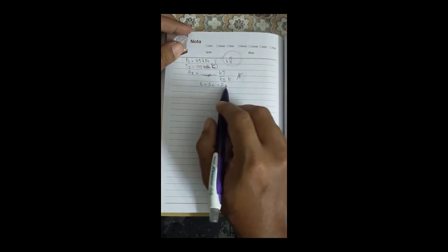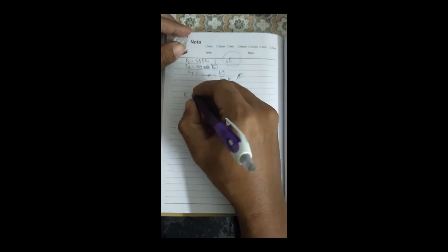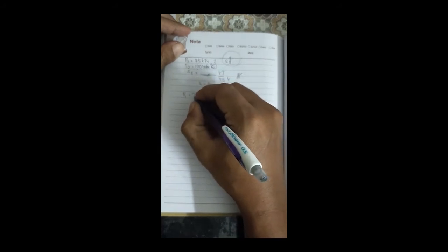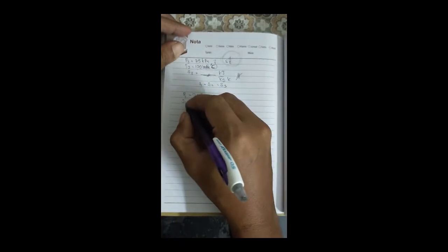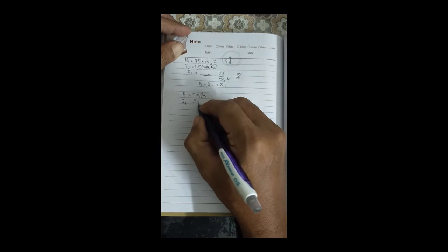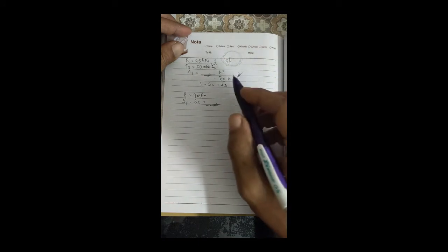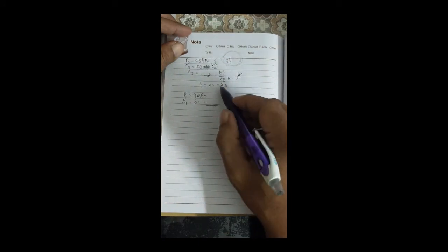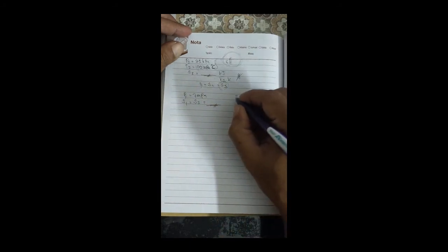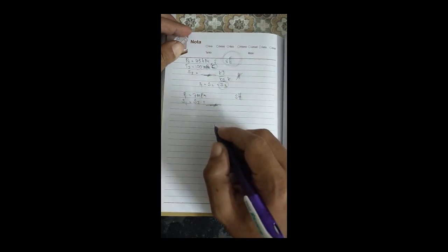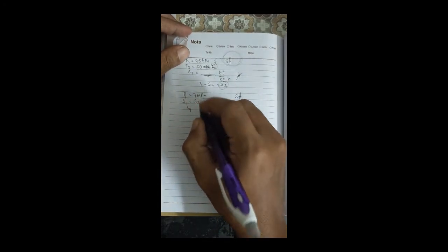So let's come back. P1 is at 7 MPa. S1 is equal to S3, equal to what amount? Logically, as your S3 is in superheated, normally point 1 also acts as superheated. So we can know the h1.